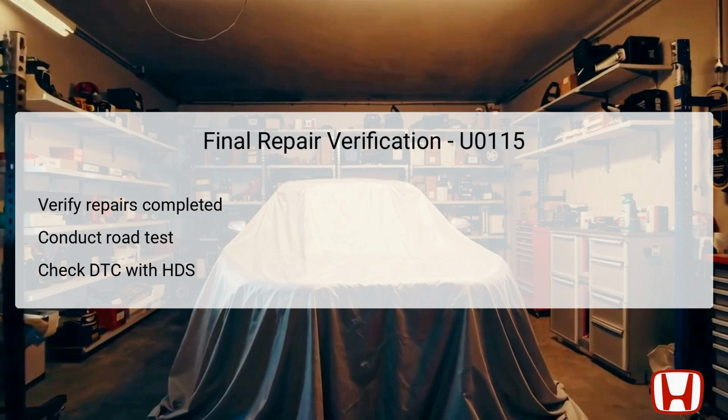Finally, connect the Honda Diagnostic System, HDS, to check for any residual or new DTCs in the system. This validation step is vital to confirm that the communication between the PCM and TCM has been successfully restored and that the vehicle operates as intended.